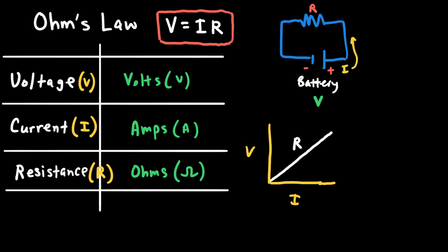If I were to write Ohm's law like this, V equals R times I, we could pretty quickly look at that and say that looks like Y equals M times X, or the equation of a line. So I'm plotting on the y-axis the voltage, on the x-axis the current. And the slope of that line should be the resistance of the material. And so long as that material's resistance doesn't change, then it's constant, and the slope of my graph should be constant.